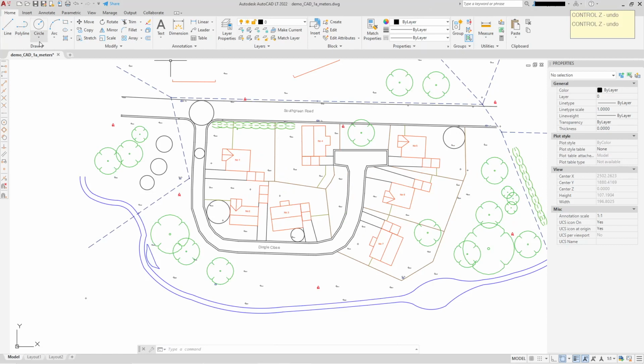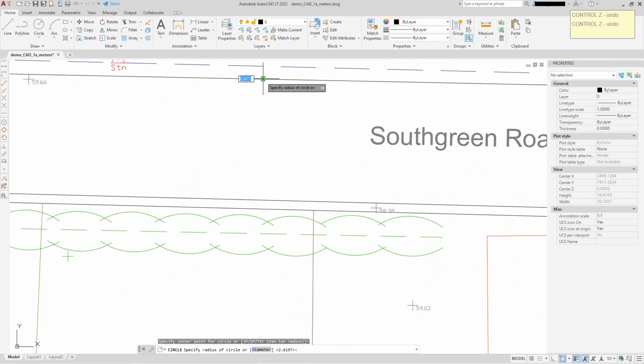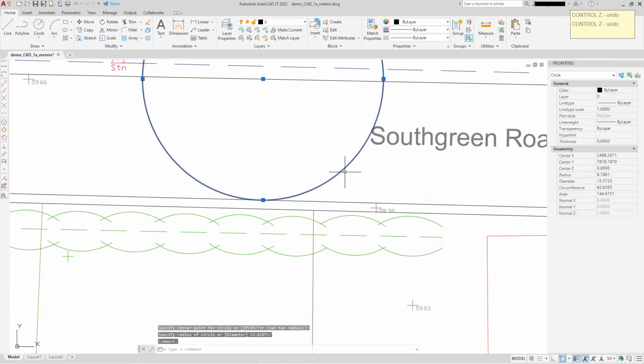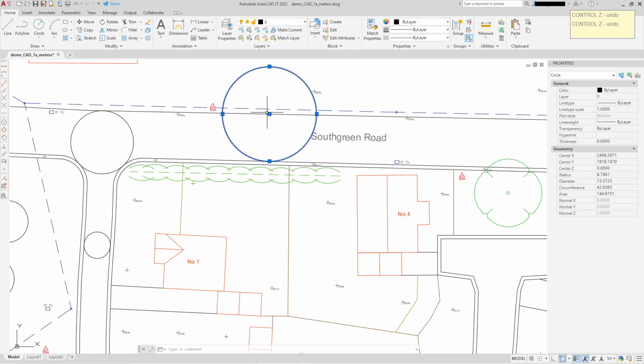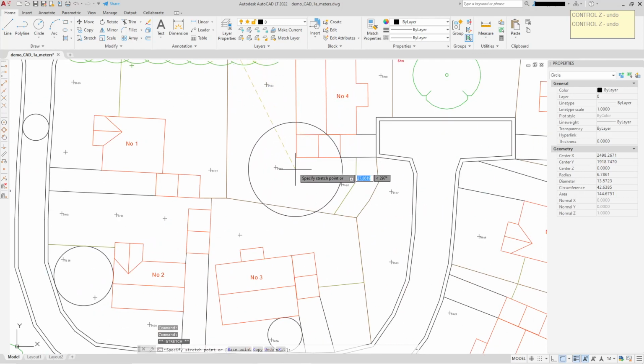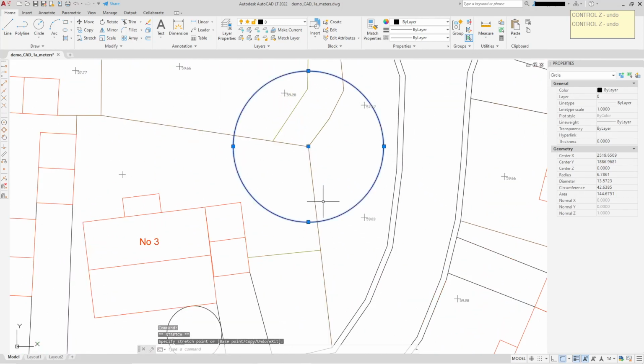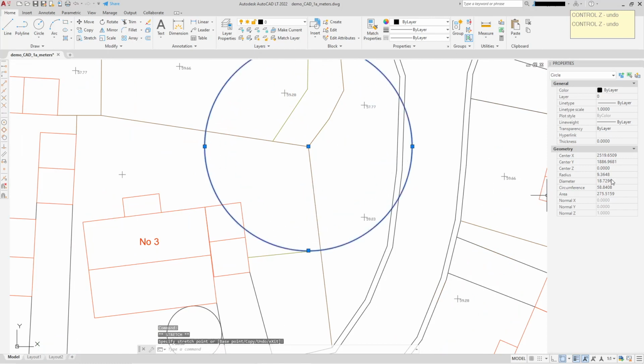And you can just use a circle for simple measuring. I used to use it an awful lot before these later AutoCADs came out. The very early ones, it wasn't so nicely prominent, so I would just select circle and read off the radius. So this road, 6.78 meters across at that point, and something else to measure, you just move it over and read off the radius again.